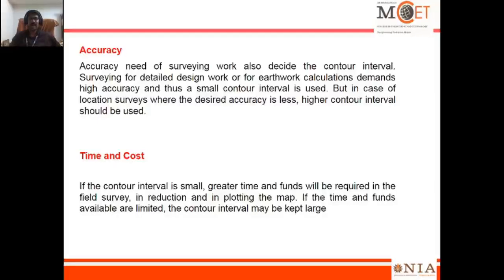And the accuracy needed in the surveying work also decides the contour interval. Surveying for detailed design work or for earthwork calculation demands high accuracy, and thus a small contour interval is used. But in the case of a location survey, where the desired accuracy is less, a higher contour interval should be used.